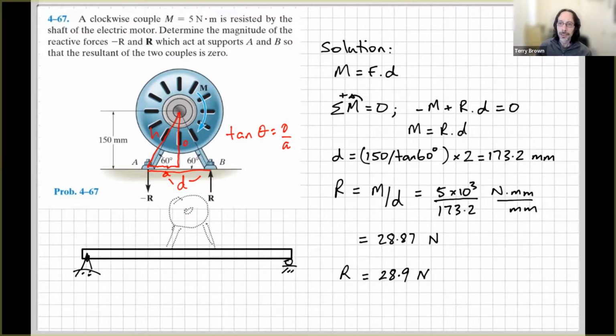What we would have acting on that beam then would be the equal and opposite of what we've got acting on the motor. So we would have loads like that acting on our beam. So then we've got an input into our beam design problem. So then you need to work out the size of the beam for strength and deflection.